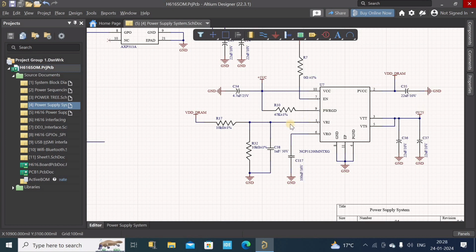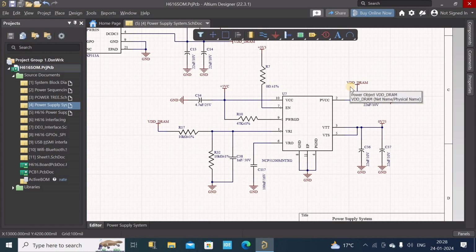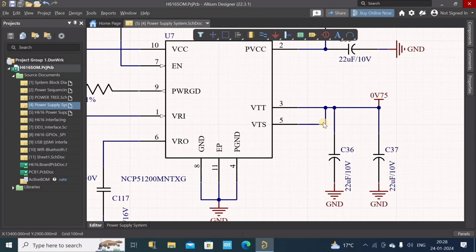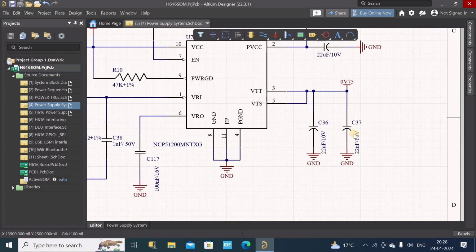Okay, this is just a reference voltage, and this output voltage has to be generated from this VDDQ. For example, if I have to use some other voltage level instead of 0.75 volt, then whatever voltage we need here has to be generated, and this is nothing but the reference voltage only. Okay, and these are just sensing pins, voltage sensing pins for proper regulation, without distortions and so on.